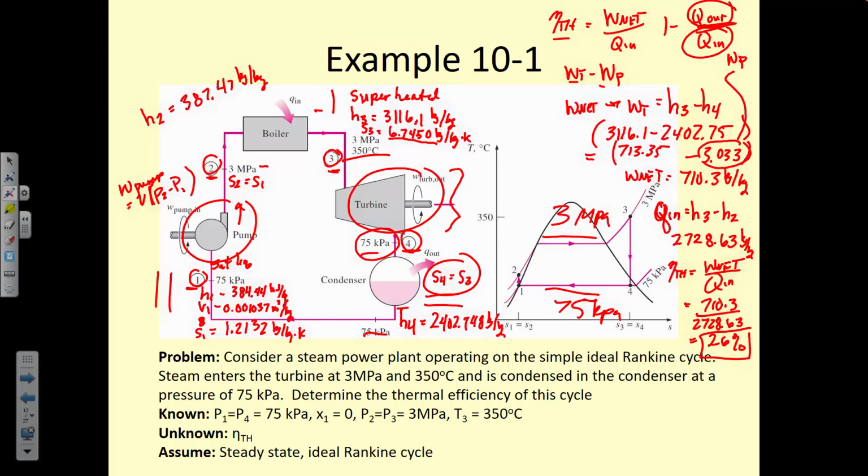Yes, right? So if you think about the cycle, here it's liquid coming through this condenser into the pump. It's still liquid, then it gets to the boiler, it gets evaporated, so it's superheated. And as it goes through the turbine and loses energy, then it is starting to condense, but it's condensed further once you get to the condenser. Does that make sense? Any other questions about that?